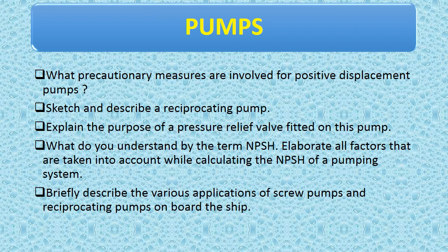Sketch and describe a reciprocating pump. Explain the purpose of pressure relief valve fitted on this pump. What do you understand by the term NPSH? Elaborate all factors that are taken into account while calculating the NPSH of a pumping system. Briefly describe the various applications of screw pumps and reciprocating pumps on board ship.